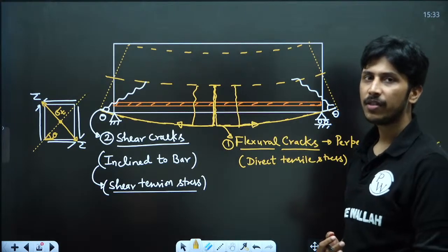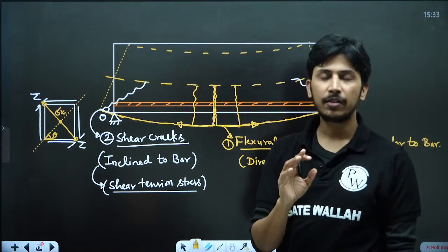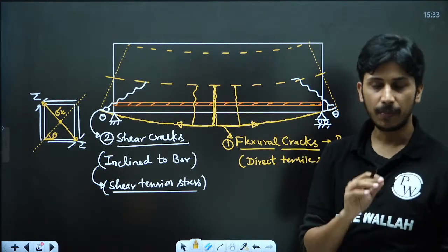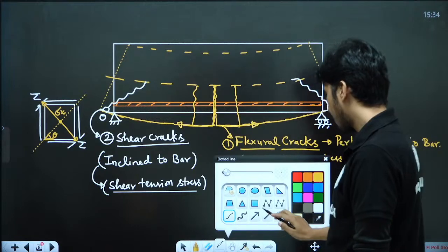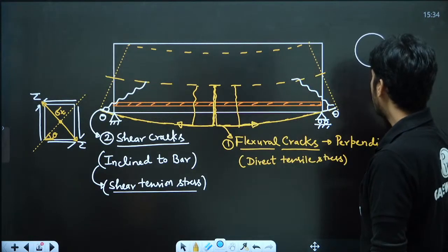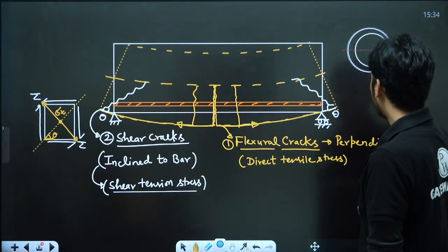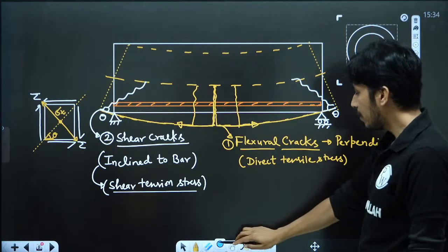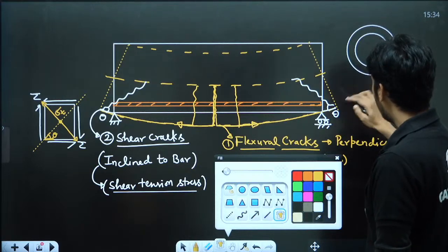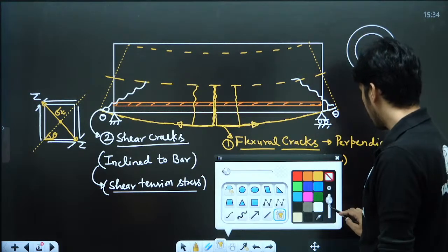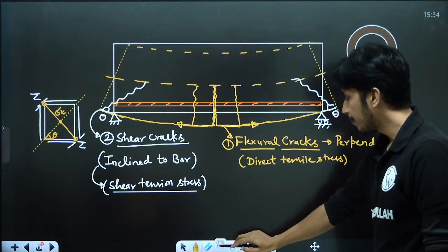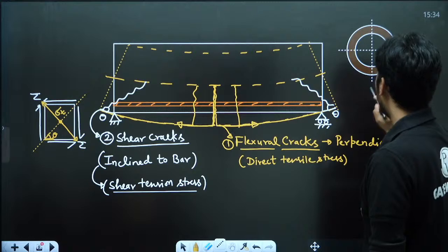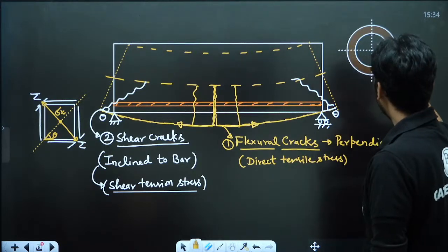Circumferential stresses and radial stresses are different. Yes, obviously. Have you studied thin wall and thick wall pressure vessels in SOM? What happens in thick wall pressure vessels? Radial stress also occurs. If your pressure vessel is thick walled, I think you must study these things. You are not studying the complete syllabus, and then you will be confused. In thin wall vessels, only longitudinal and hoop stress is there. Hoop is circumferential. So if the vessel is thin walled, only two stresses are there.